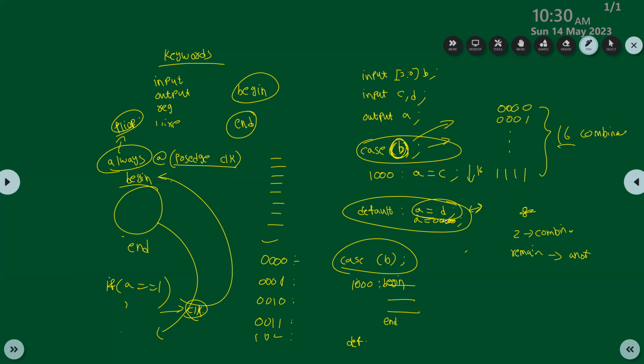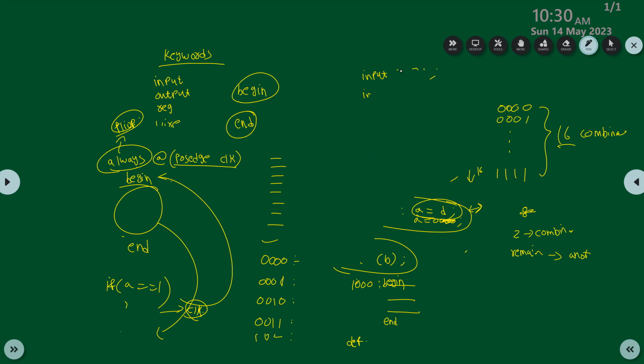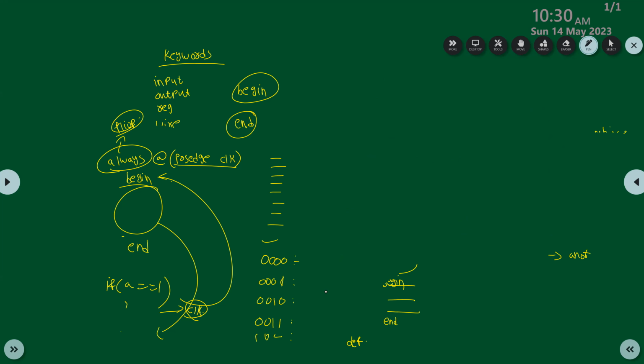Default cases will depend on whatever values you wrote in the normal case statement. Don't forget, if you're writing in binary in the case, you have to give 4-tick B0 always. Let's take this example. Let's say I define a wire W1, which means it is a single bit. If I write a case of W1, it will consider all combinations of W1: 0, 1, Z, X. Let's say I write only 1-tick B0, then I write some operations.